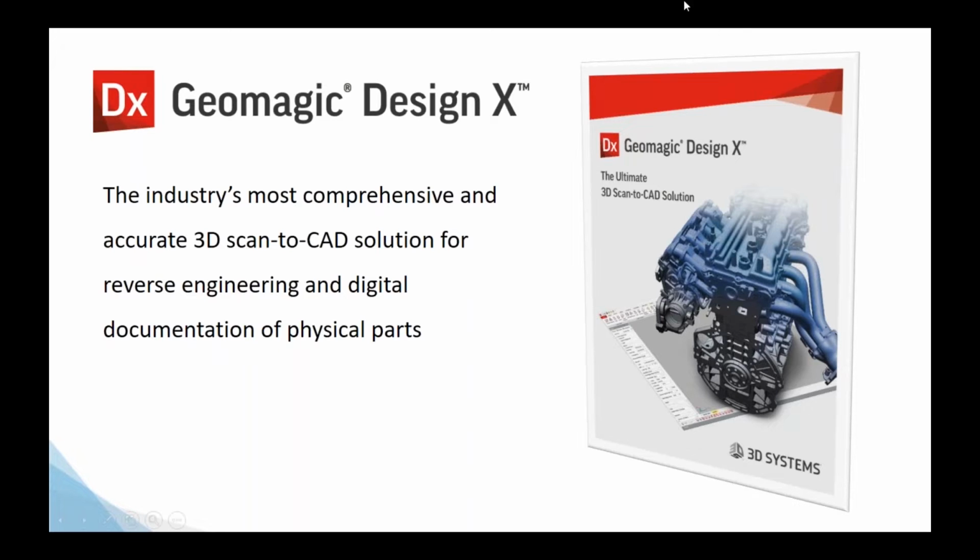Just a quick plug for what we're going to be taking a look at today. Software-wise is our product called Geomagic Design X. This is our flagship reverse engineering software for converting either point clouds or, more commonly, 3D scanned mesh objects into a history-based CAD model that's compatible not only as just a dumb solid, IGES or STEP or Parasolid export with things like SolidWorks and other CAD systems downstream, but also can generate native files.